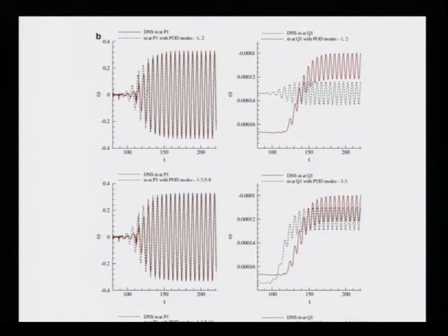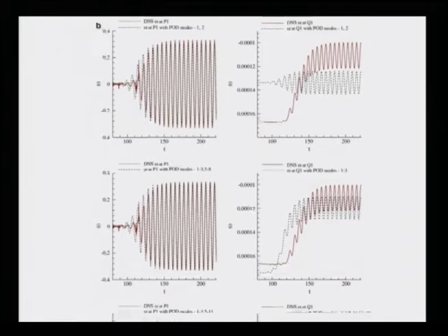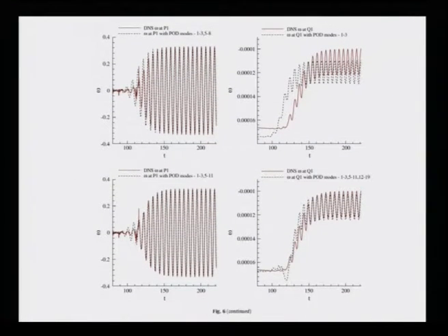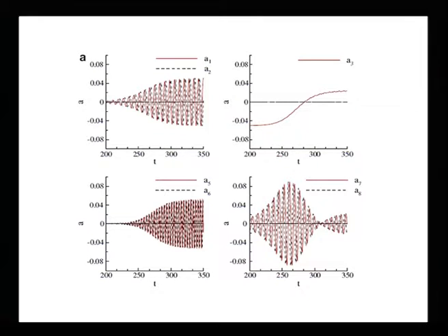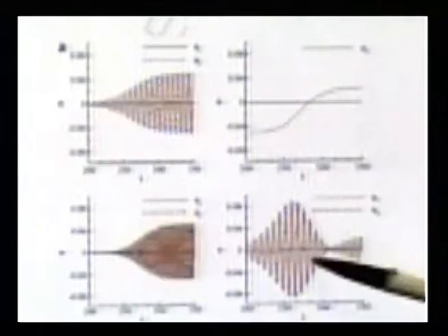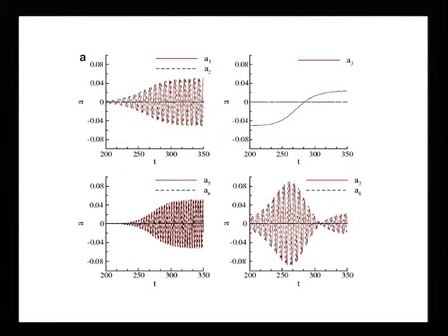These are those mode shapes for cylinders. Anyway, what we are essentially looking at is a mode shape for flow past a cylinder at Reynolds number of 60, and again you can see these two are those regular modes. This is the T1 mode and this is a T2 mode, and so on and so forth. So you can study this as a sort of universal building blocks. Okay. So I think what I would do is close the discussion here on POD analysis. I suppose you have now seen quite a bit of variations.